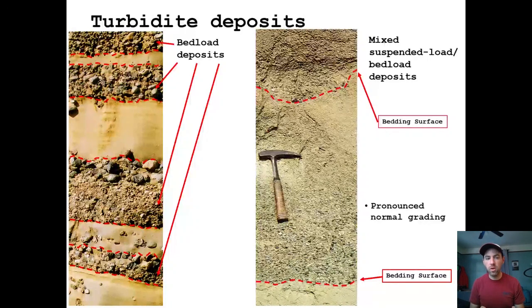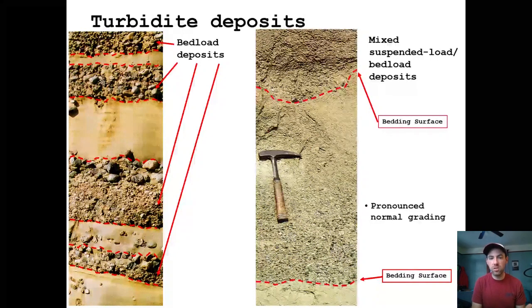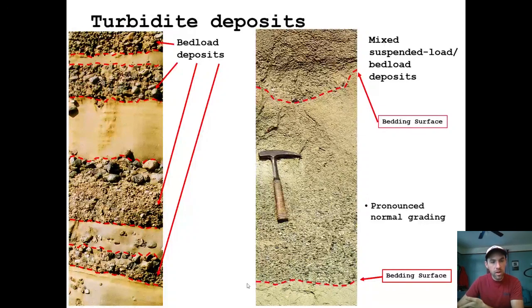And in particular, in turbidity current environments, they go from coarse grain sizes to reflect that high energy, high shear stress, high sediment concentration head. As that head passes you and you drop out that coarse sediment, first off, you get scour oftentimes at the base, right? So as the first part of the turbidity current passes by, it may erode sediment, right?